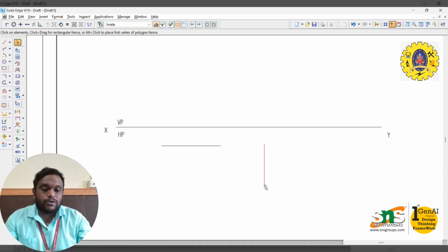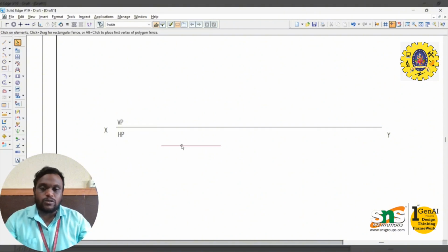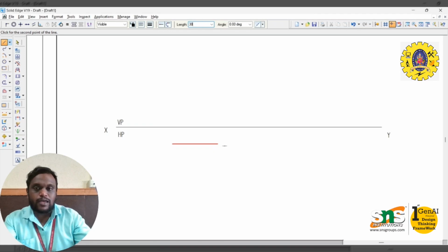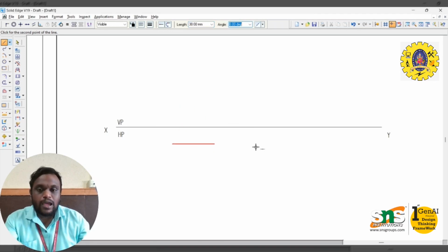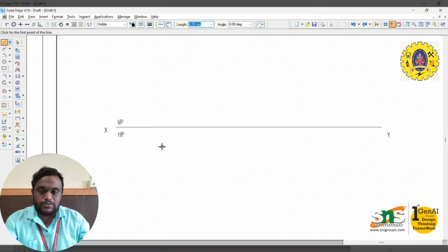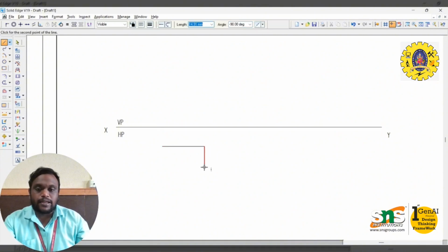So now we will carry it out in one way of projection, that is, one side parallel to a reference plane. So I would like to draw this kind of surface. The surfaces are about 30 mm. So I have to mention 30 mm, and I have to draw like this. This makes one side of the hexagonal prism 30. If I draw it as an axis, there is no problem. If you click it, it will automatically change into 30 degrees. Then the difference between the two sides will be 90, and again I have to rotate this way.